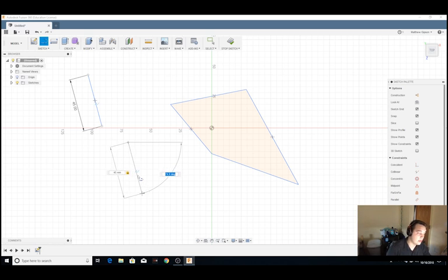This is because I've already selected the 45 and now I'm trying to pick an angle. I can pick it by just moving the mouse around, whether I want an obtuse or an acute angle or 180 degrees. Or, because it's blue, I could just type into the highlighted box that I want a 25 degree angle. And there, voila.